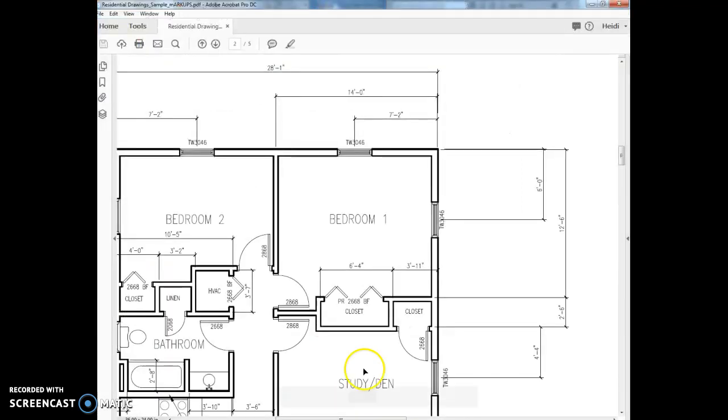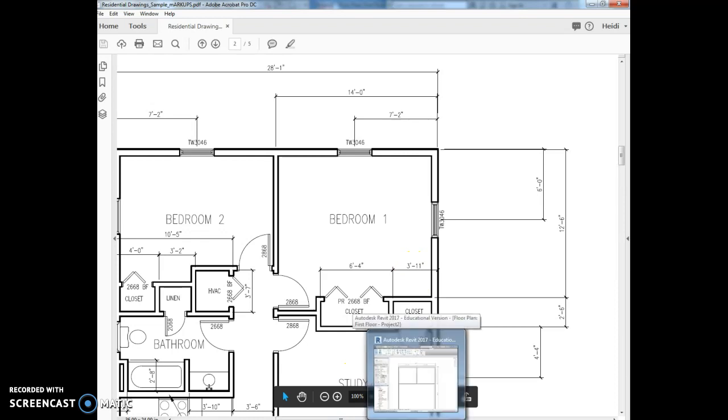So you just really need to carefully look at the drawings and where the dimensions are running to so that you get the dimensions correct. For the closet, make sure that you're starting from that 12'6" dimension and that you're going back down here to the inside of the wall for the closet depth, which is 2'6". The width of the closet is from, again, the exterior face of the wall to the interior face. So just make sure you're paying attention. You have to draw the wall, and then you have to do the dimensions to make sure that your dimensions are right, and you can use temporary dimensions to adjust your walls. I'm going to leave that to you guys to work on.